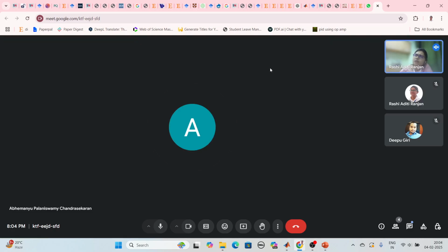See, the basic concept of chaos actually comes from the time dependence only. However, in the phase plot, it will cover more area and it will not have a neat response. For a periodic response, in steady state, you always get a neat response, a circle or maybe two circles. But in the case of chaos, you will never see that. For more complicated systems like the ones we work on, we get a random shape which is totally filled in, like in a phase plot, because of chaos. So from that also you can identify.